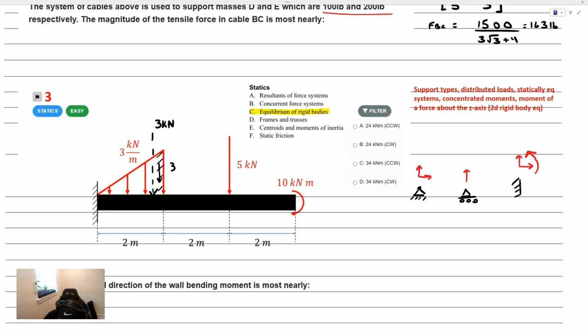You could place its total force at that little area centroid. That'll be this large force placed at a close distance, and the small area is also producing a moment here, but its centroid is closer towards the left side, or it has more distance compared to the large area, right? So this small force placed at a large distance must balance this large force placed at a small distance.